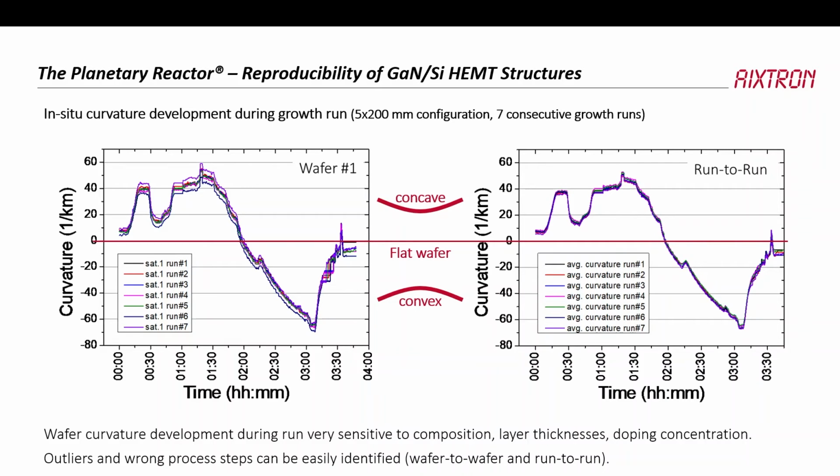This is also an interesting measurement, and here we are again in yield territory, when we compare the different wafers, because an outlier, a bad wafer, a bad egg, will directly show, because it will completely go astray and have completely different properties. So from that point of view, the curvature measurement is also a very good tool to assess how well your run performed and how your wafers have performed in this run.